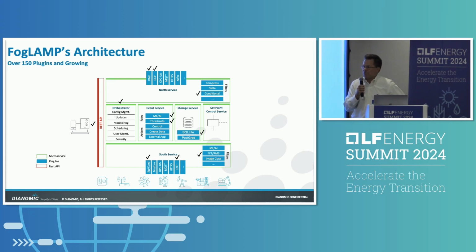There is no usual, since it's just microservices. We've tested it, and we do test it on Raspberry Pi Zeros as a footprint. But since you can containerize it, we have probably 30% of our implementations actually implemented in the cloud. So a really common one for lots of industrials is they have different services companies doing route-based monitoring and so forth, and that data usually is available through a REST API. So if you're going to do a REST API integration to a historian or an MES, it's usually pretty convenient to do that in the cloud. If you saw the JEA use case, there were 4 of them that said REST APIs. So that's how they were done.